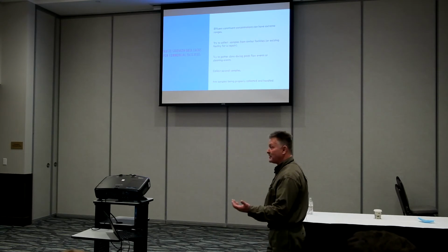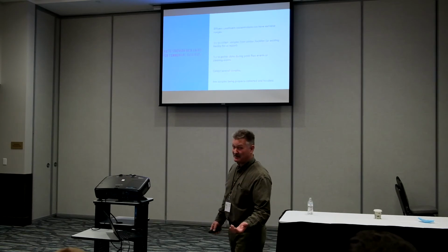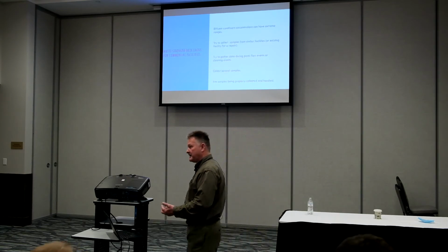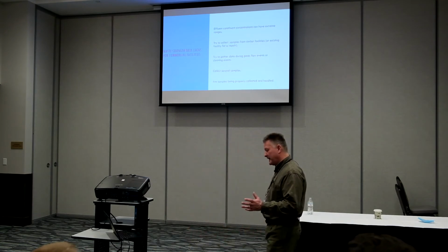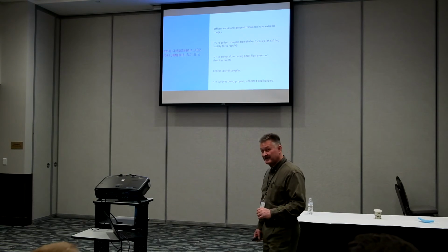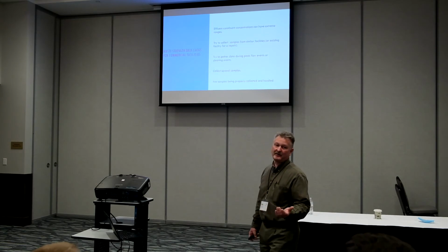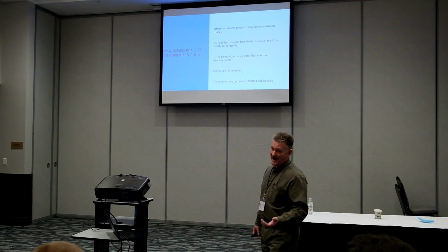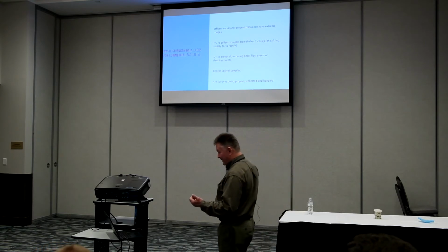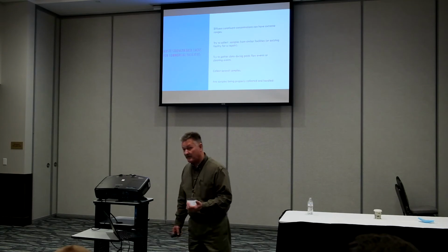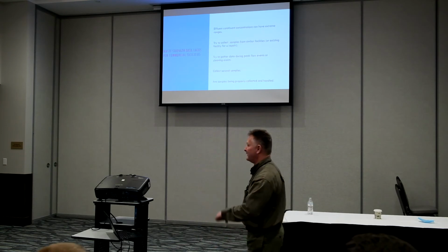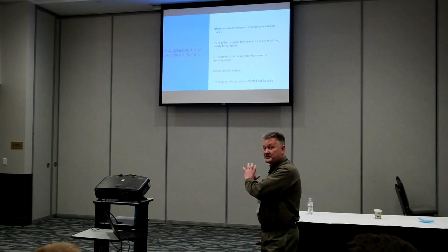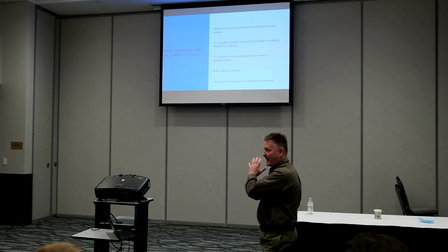And you want to make sure that whoever is collecting the samples is collecting them properly. I was reviewing some data the other day on a couple of treatment systems, and I know the service provider really doesn't collect samples on a routine basis. I looked at their data, and the influent was way out of whack on 3 out of the 4. So I need to go back and talk to them about how they sampled that, because I've seen them use pop bottles on a string, get it in there, and put it in the back of their truck. I want to make sure that what we're designing by are good, valid data points.